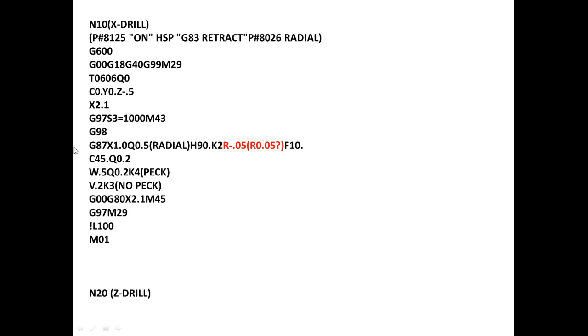Okay, so that's a Mitsubishi control or Fanuc control, two different ways. Mitsubishi, we have a G890. That's how we do the spindle phasing. So spindle phasing is different than the sub-spindle C-axis position, if that's the question.